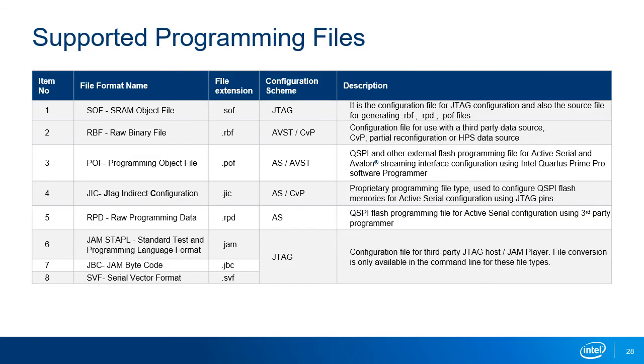This table shows the file types supported for Agilex FPGA configuration. The new configuration schemes use existing file types. Hence, there are no new programming files for Intel Agilex devices. Let's go over these file types in some detail.